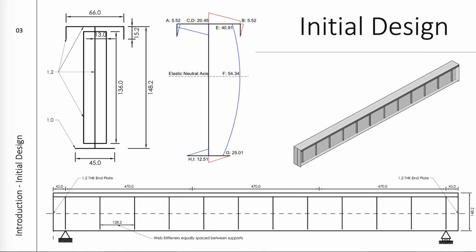In order to reduce the stress in the top flange, it was decided that the section would be asymmetric, as shown, causing the centroid of the section to move up the cross-section, reducing the stress in the top flange and thus the risk of local buckling. Additionally, lips were added so that the flange could be modeled as having simple supports and better resist buckling.